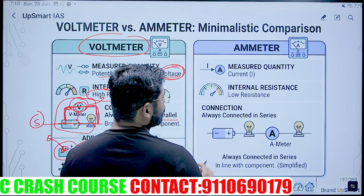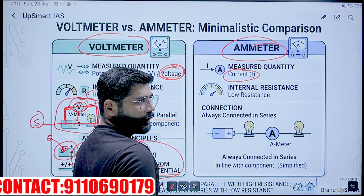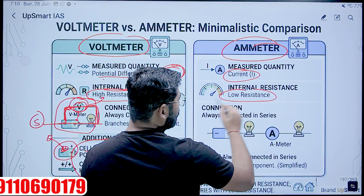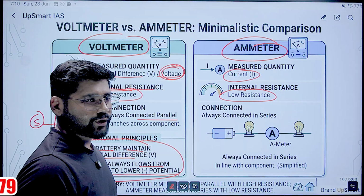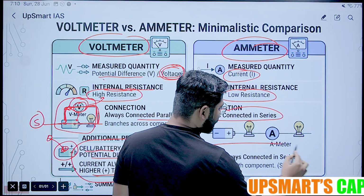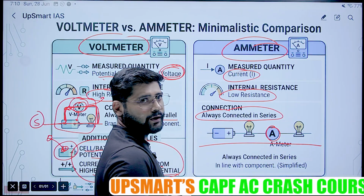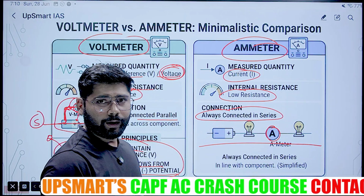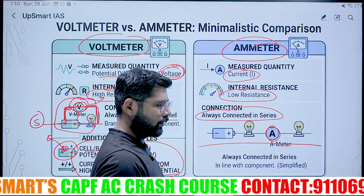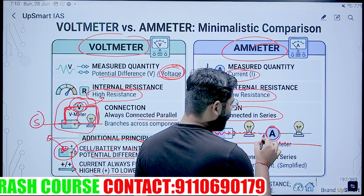Next is the ammeter. What does an ammeter do? It measures the current, and it has low resistance. Why does it have low resistance? Because the ammeter is always connected in series. Here is the series where we have connected the ammeter within the circuit. Now there is a current flowing within this circuit.